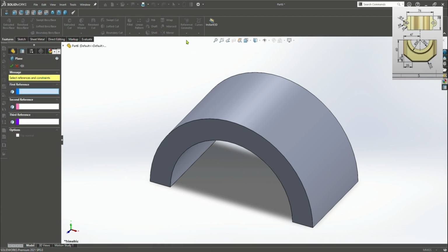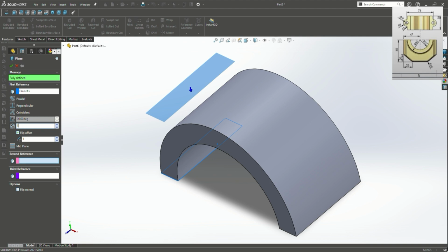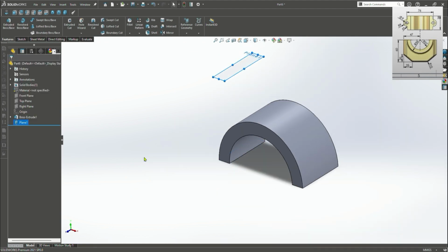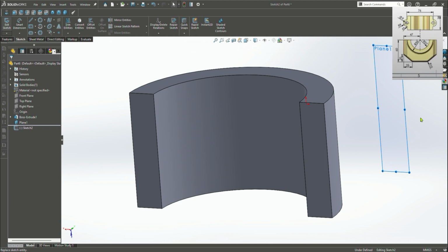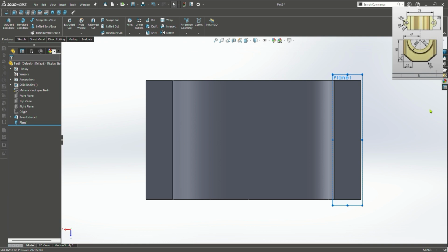So we need to add a plane as our reference plane. So 60 mm. Okay. So from this plane, we are going to sketch referred by this plane. We're going to sketch a slot, a combination of two circles and two lines. Okay.